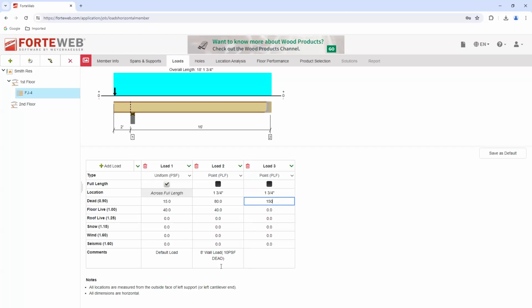And then depending where you're at location wise, you have 2 categories. You have your roof live and then your snow. If you're in an area like me that has a snow load, that acts as my roof live load. If you're in Texas, Florida, places that don't get snow, you just have your regular roof live load, and it's taken at a different iteration than your snow and your wind. So for the snow load, I'm going to take that 40 times 10, which is 400. And then I'm just going to put in here my notes so I know what's going on.